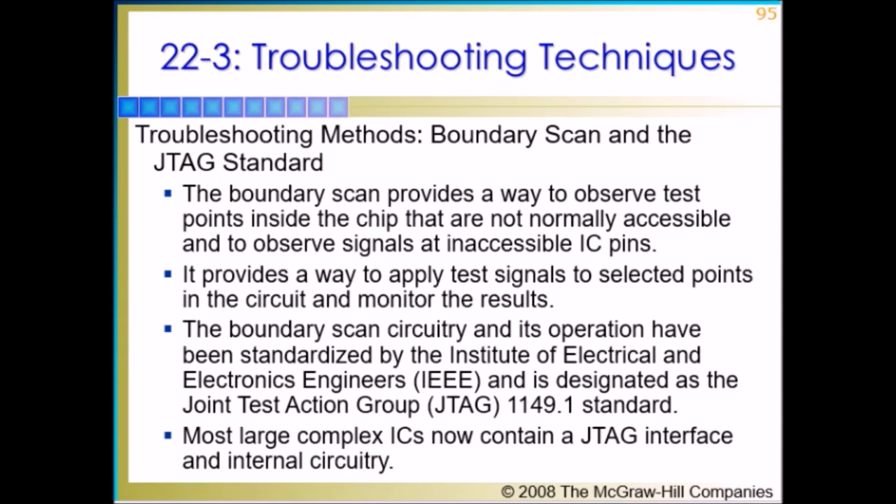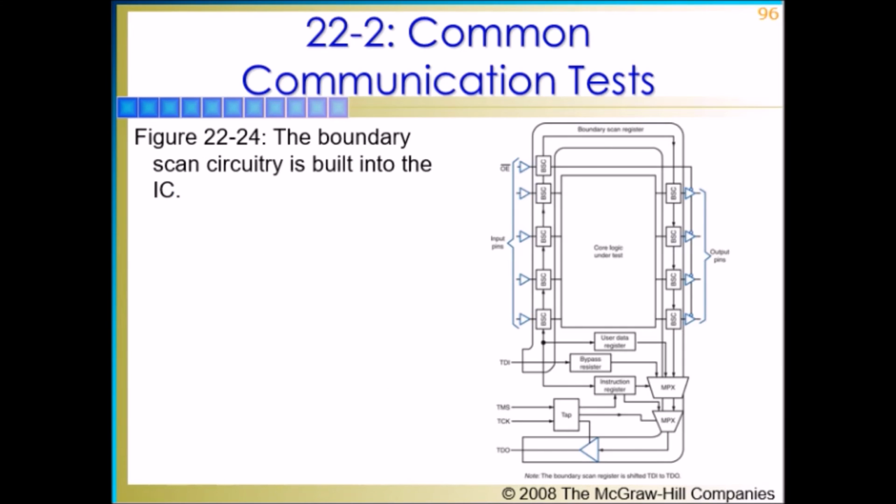It provides a way to apply test signals to selected points in a circuit and then monitor the result. As the figure shows, boundary scan is circuitry that is built into many complex ICs.